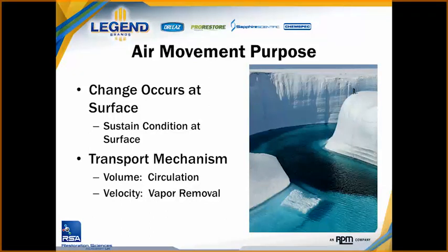Because as the ice begins to melt, even though the water was at 20 C, the liquid melting off of the ice is going to be extremely cold right around the surface of the ice cube. It's going to form what we call a boundary layer. And now cold water is next to the ice, not warm water. So we have to cause flow inside the bucket. You take your hand, put it in the bucket, and start stirring the water around, and the ice cube is going to melt extremely much faster.